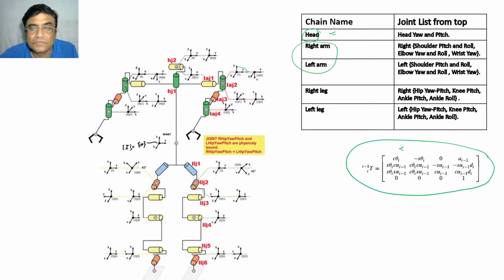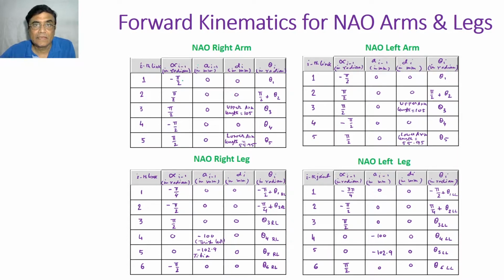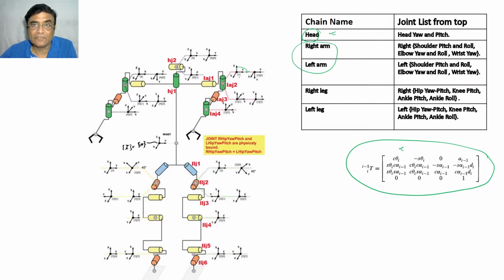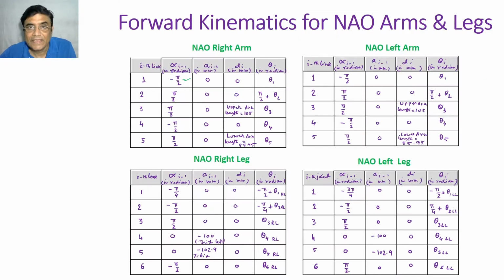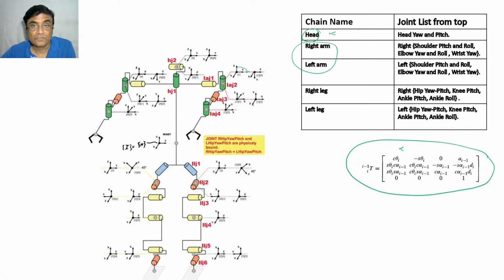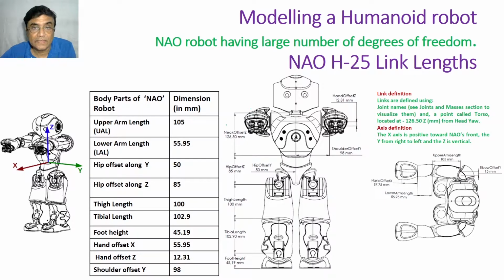So this has been depicted here, and all other parameters are 0 except theta 1. So that's how the coordinate frame has been attached. You must know this, and just go back, see how the coordinate frame is attached, and carefully verify that these are correct. This is very important to have this table drawn very correctly. Any mistake you make will be dangerous.